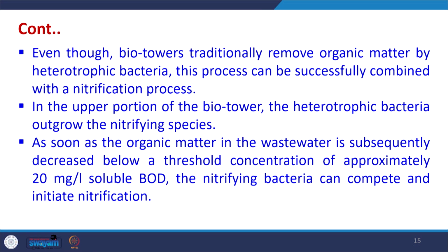Even though biotowers traditionally remove organic matter by heterotrophic bacteria, this process can be successfully combined with the nitrification process. In the upper portion of the biotower, the heterotrophic bacteria outgrow the nitrifying species. As soon as the organic matter in the wastewater is subsequently decreased below a threshold concentration of approximately 20 mg per liter soluble BOD, the nitrifying bacteria can compete and initiate nitrification. So, we can have first the removal of carbon content and later on the removal of nitrogen content.